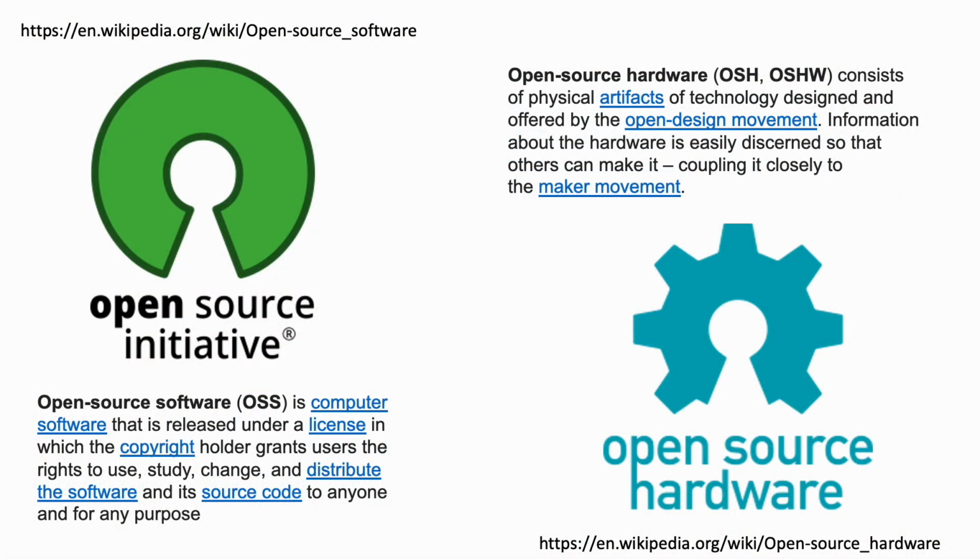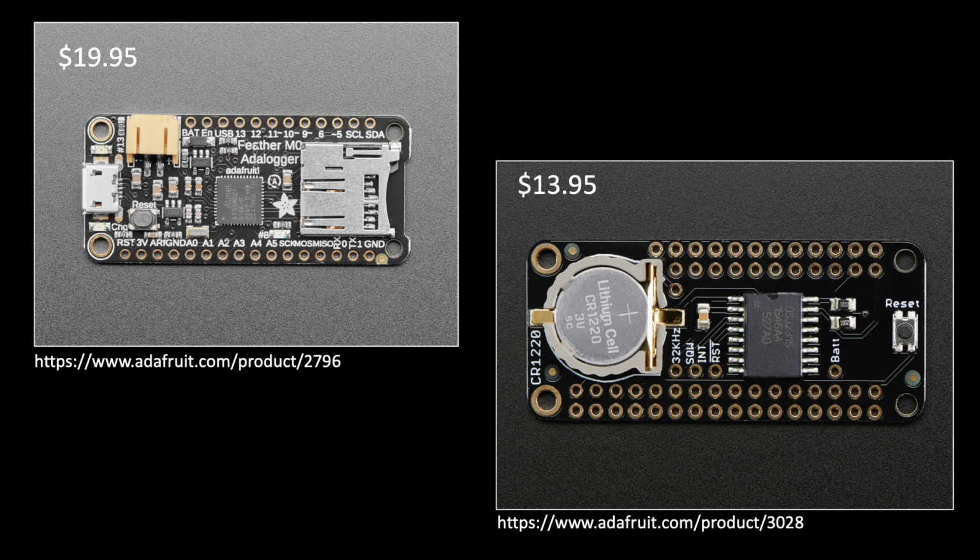Open source alternatives make royalty-free platforms available to makers innovating in science and technology, with hardware options available through electronic vendors such as Adafruit and SparkFun. Our data logger takes advantage of the same by coupling an Adafruit Feather M0 data logger with a DS3231 real-time clock, both of which rely on open source libraries for programming.